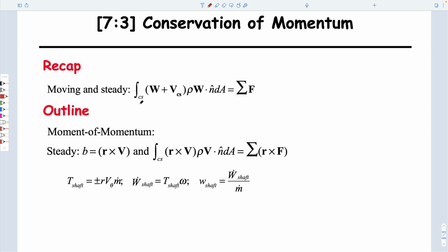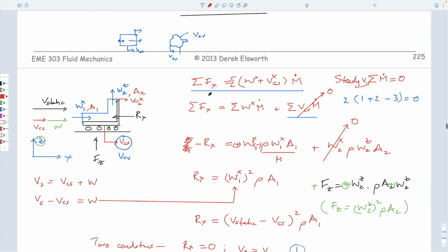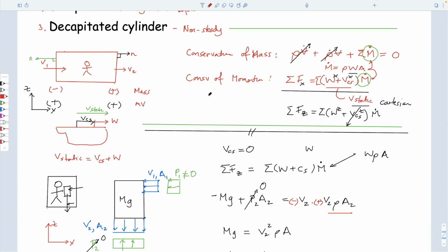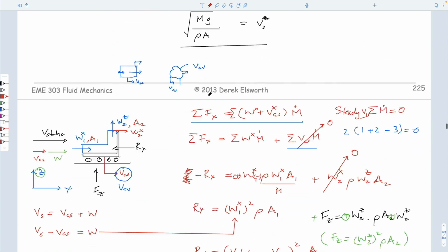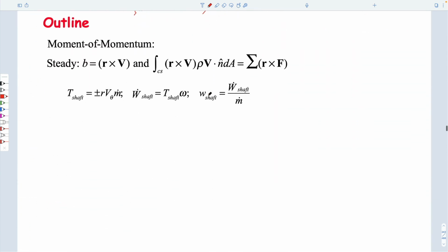All right. So that's kind of the 5-minute summary. So this is our linear momentum equation. We've replaced this integration really by a summation on the boundaries. If we do the summation, then we can get rid of, ignore, this normal term because we take care of it by looking at these directions. And all the dot product says is if the vectors are in the same direction, their vector product v dot n is 1. If they're opposite directions, it's minus 1. If it's perpendicular, it's 0. So that's the behaviors that we would look at. Okay, so the rest we don't need. All right. So moment of momentum.